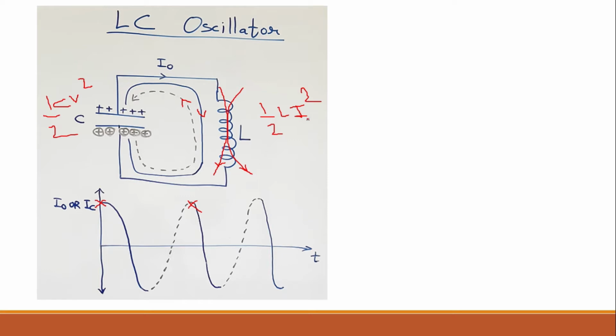So this is known to you, but the waveforms you see here are sustained oscillations. Exactly, this LC oscillator will not give such sustained oscillations. Why? Because there will be losses in every cycle due to the wires connecting the capacitor and the inductor. There will be losses due to the resistance of the inductor, as well as due to the dielectric material of the capacitor.